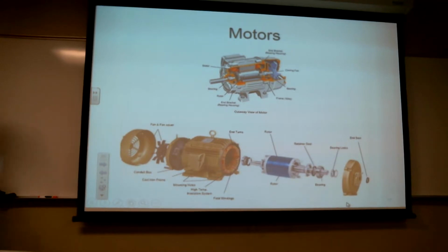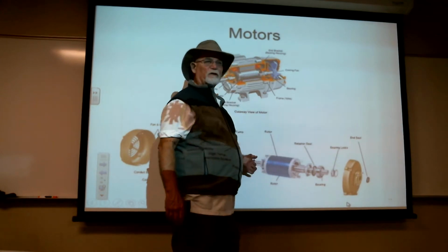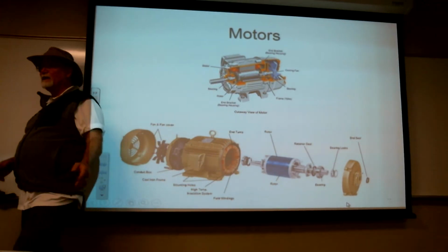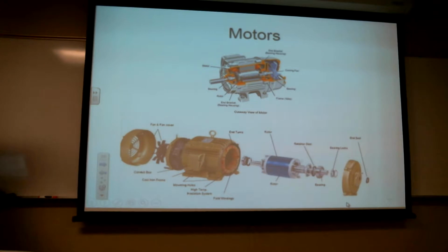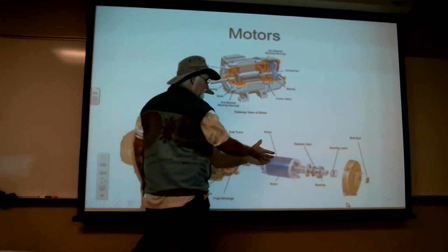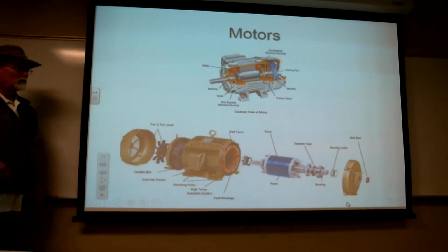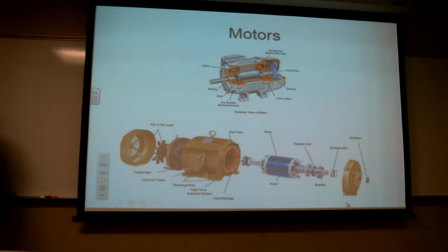Oh yeah, so here's a picture of a typical squirrel cage induction rotor. No brushes. No brushes are needed because we're going to induce the current. This AC field is going to induce current in here. The current that's induced in here will create its own magnetic fields, which will try to follow that original AC field. That's kind of confusing, huh? Sort of seems like perpetual motion. But as long as there's some slippage, it works.